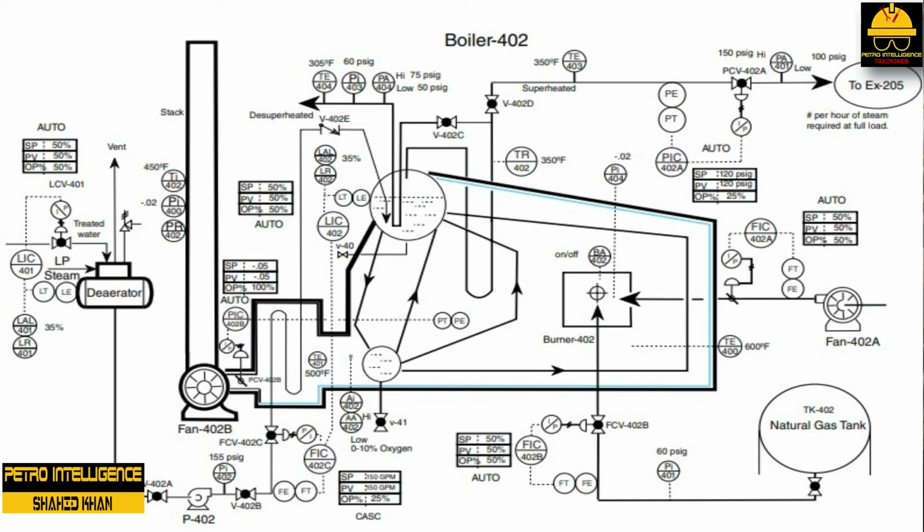2. Ensure all safety hazards are secured: trash, locks, old permits, etc. 3. Check equipment and instrumentation: stroke control valves 0 to 100%, check lineups, etc. 4. Line up P402. 5. Set FIC 402C to 150 GPM and place controller in cascade. 6. Set LIC 402 to 50% and place controller in auto. 7. Set PIC 402A to 120 psig and place in auto.